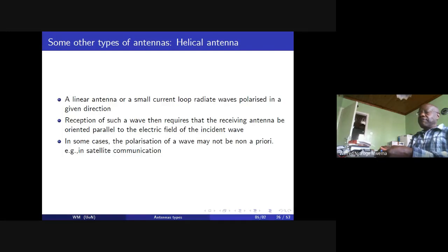This is usually referred to as Faraday rotation. The direction and the amount of rotation are not known, it's random, because the conductivity and the magnetic interaction with the Earth's magnetic field is usually a random process, and therefore we will not know which polarization the wave arriving on Earth has.